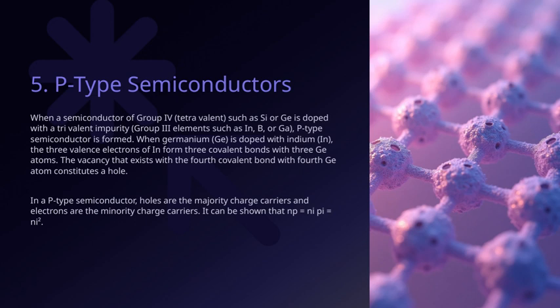Essentially, doping introduces these holes, which become the primary carriers of positive charge, enabling the semiconductor to conduct electricity in a controlled way. So, in summary, doping with a trivalent element creates holes by creating these vacancies, making the material p-type, with holes as the majority carriers. And this concept is fundamental to how semiconductors are engineered for various electronic devices.